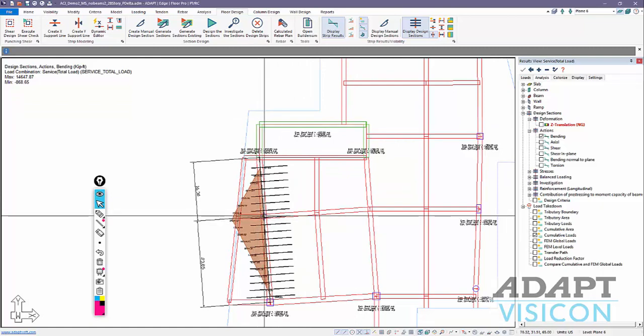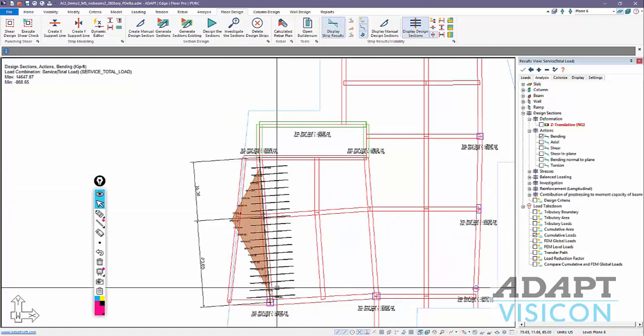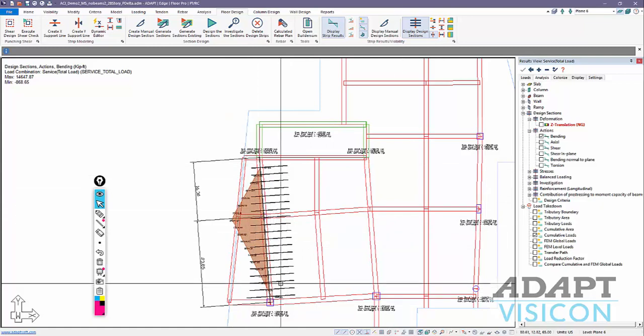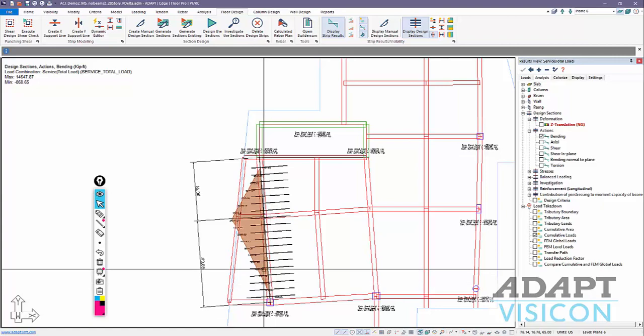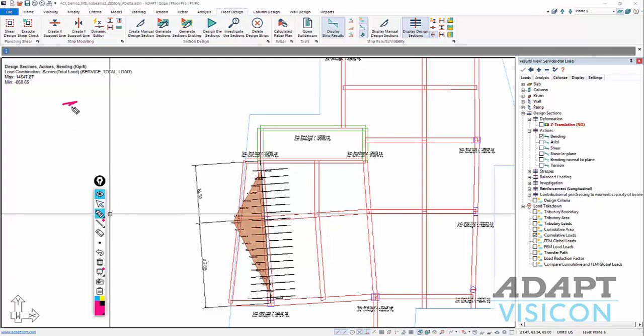In this case, you have more of a one-to-one relationship in terms of the load going to either component purely based on tributary. So when we run this design, we obviously would get something different in terms of the rebar. We may need to add more post-tensioning. It's really up to the user how they want to approach the design using load takedown, which is just a method where we can quickly accumulate the loads based on tributary, or using the finite element approach that we ran previously. The third way to do this is, I'll call it an indirect approach, and it's using the FEM reactions.